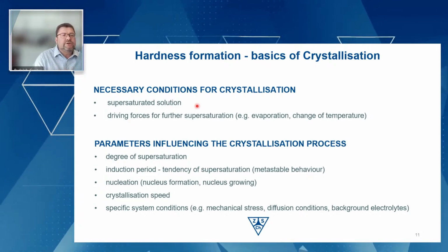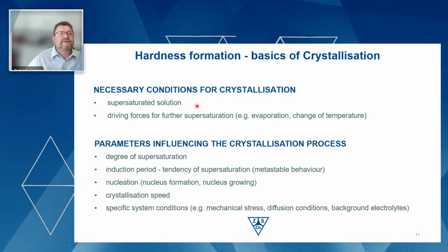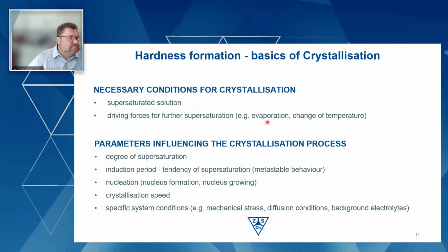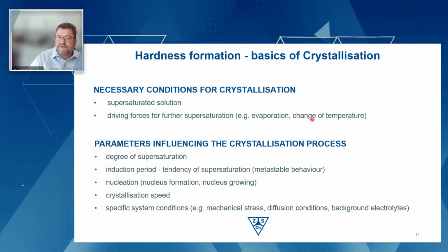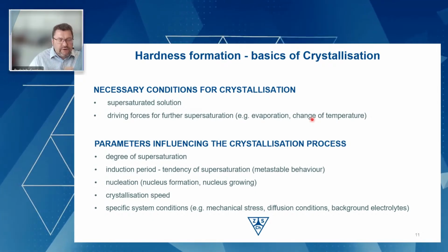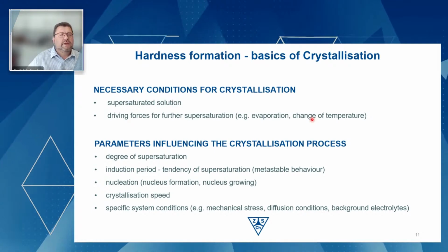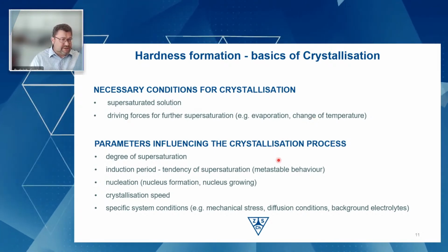The supersaturation can be driven by different forces. This can be by evaporation, so something of thickening, for example, also change of temperature. If you remember on this heat exchanger, it's the hot spot in the system, and at the hot spot we have this chalk formation.